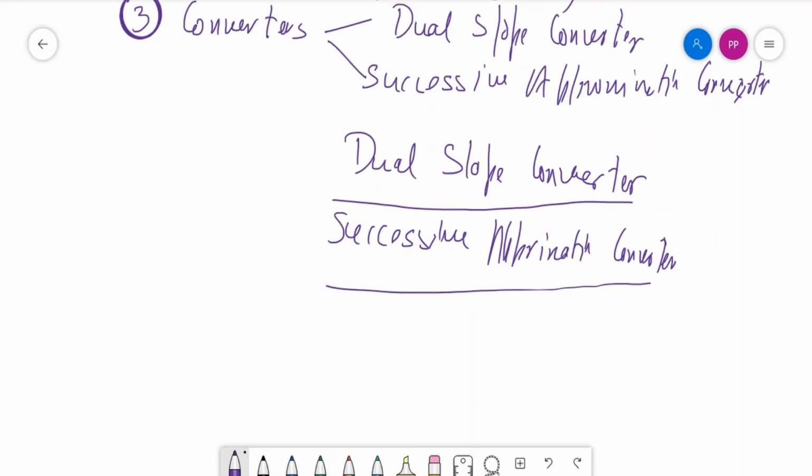As we can recall, the first half of the voltage, that is 5 volt, will set the MSB, while the second half of the voltage, that is 2.5 volt, will not set the register because the remaining voltage from 7 volt will be 7 minus 5 equal to 2. So this second bit after MSB will be reset to 0. Similarly, all the 8 bits are set or reset, and thus this process of conversion has a fixed time of